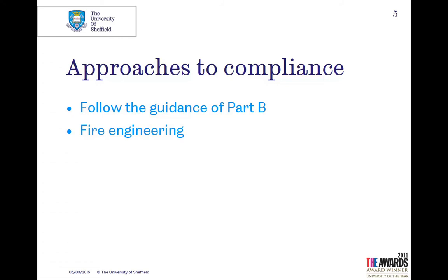It can also be a cost saving, because although you have to pay the fire engineer's fees, you can sometimes save money on the build, because you can maybe have fewer stairs, or you can have slightly lesser performing materials, because you're demonstrating that it still works. And I've had a few projects where we actually saved money. We paid a fire engineering firm maybe £5,000 to do some engineering for us, but it meant we could take out a stair, we could take out some fire glazing, and it actually saved the client money.